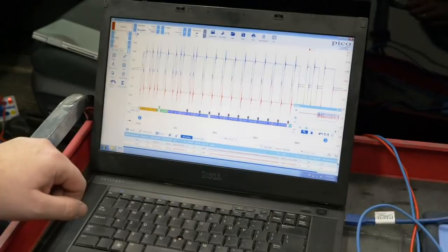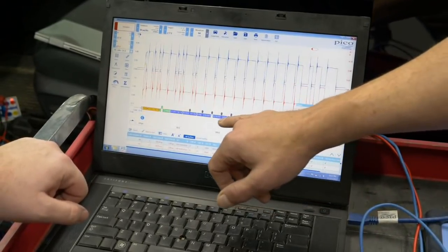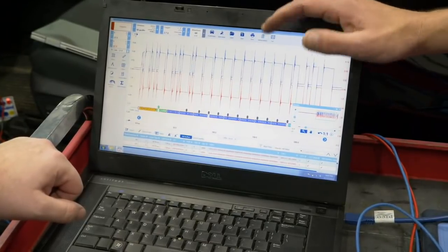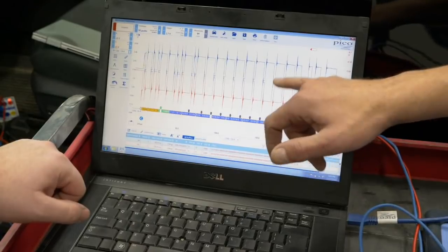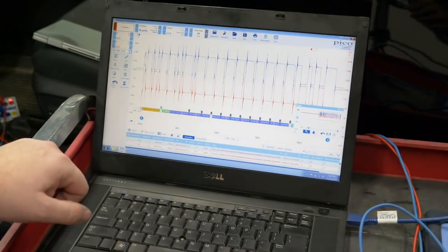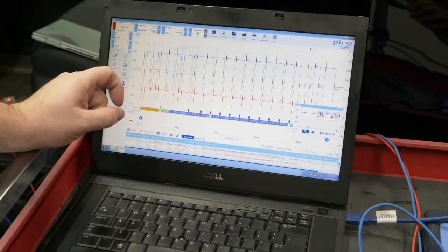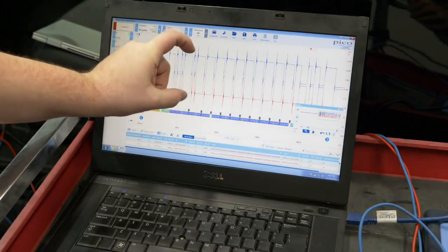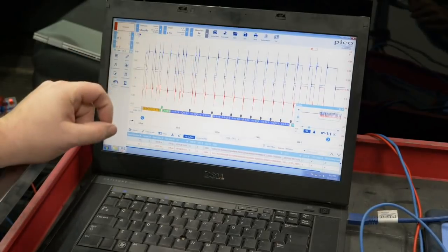It looks to me like the binary is a little bit opposite what a lot of people would expect, because it looks like the zeros are a high voltage, like an on in my square wave, and the ones would be the off or the lower voltage. Is that what I'm seeing here? Yeah, that's correct. The CAN network's very interesting in that it has a dominant and recessive state, and those get translated to, I believe, the dominant state being 0 and recessive being 1.